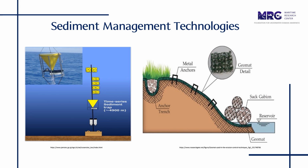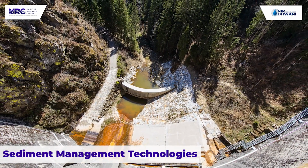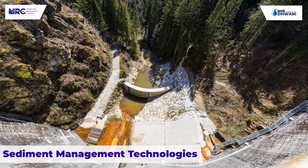So there are various erosion control techniques which include the placement of large rocks along the banks or river banks to prevent erosion. There is the use of geotextiles, which are synthetic fabrics used to stabilize soil and prevent erosion, which would decrease the sediment influx into the water systems. There are also sediment bypass systems which include various tunnels to divert sediment-laden water around critical infrastructure such as dams to prevent the sediment buildup.